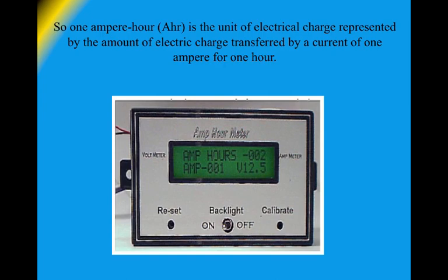Of course, measuring specific gravity with a good hydrometer is a good method of determining a battery's state of charge, but as we all know, having done it, it is messy and it requires you to introduce the hydrometer into each cell of the battery. This can lead to cell contamination, and as I just mentioned, it's quite a messy procedure.